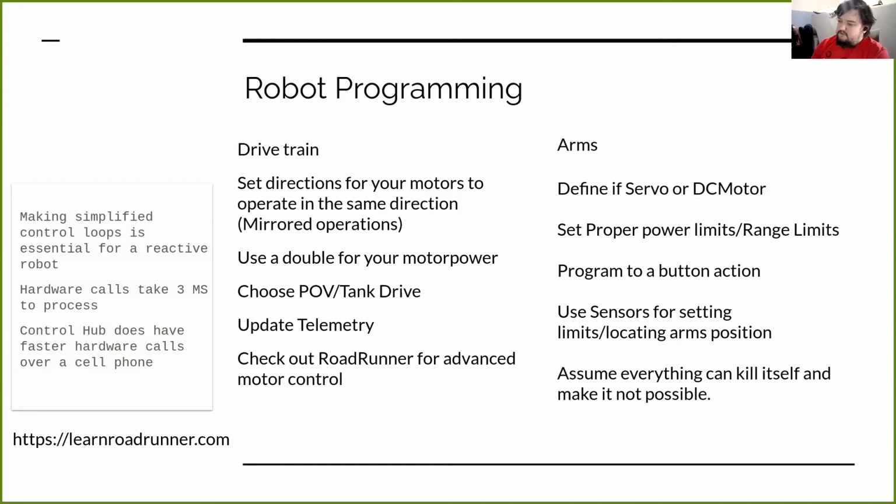So as long as you set a software limitation before a hardware one, you're going to make your parts last longer, and you're not going to break something on competition day. And that becomes a huge benefit for when you do autonomous programming, because now your robot needs to know where its own objects are so that it can't break itself.